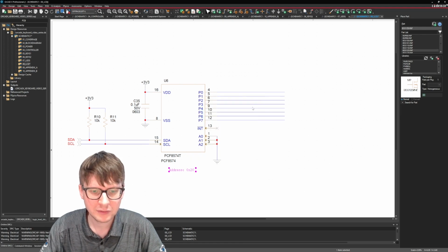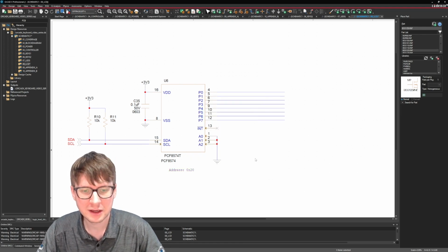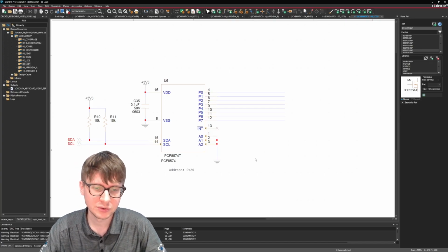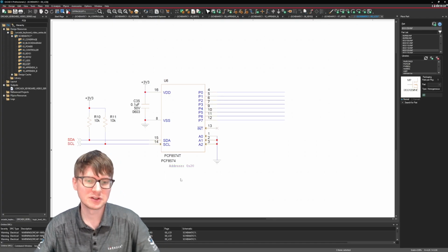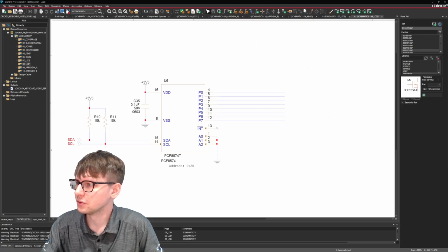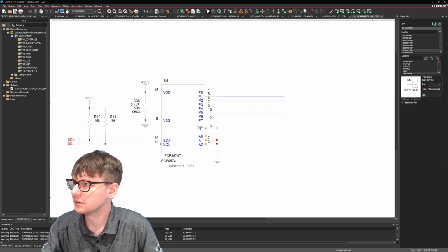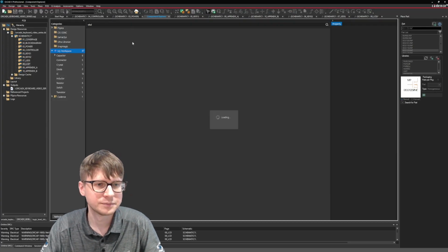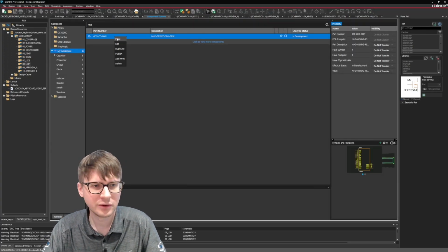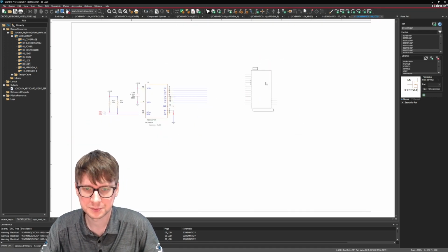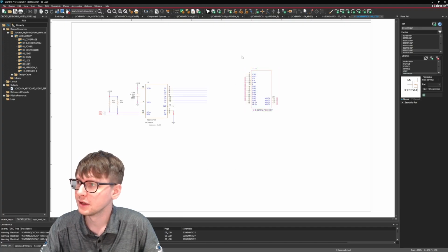And if you're programming, you can always double check by, if you have an I²C address, it's called an address sniffer. You can see what all the I²C devices connected to your I²C bus are. But it should be 20. All right, so the next thing we need to do is add our LCD. So it's NHD. This is an LCD from New Haven Display that I've used probably about 1 million times on a bunch of different projects. We're going to go ahead and hook this up here.